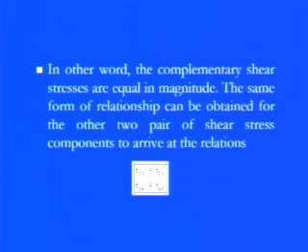So irrespective of which domain we are working in, the shear stress components are always equal in the respective directions if we consider the symmetry, and if the objects under these forces are well maintained in equilibrium. We discussed that if we have a general state of stress, we need 9 different components: 3 normal stress components and 6 shear stress components. Even if we apply the symmetric conditions, we need only 6 components to describe the stress: 3 normal stress and 3 shear stress components.